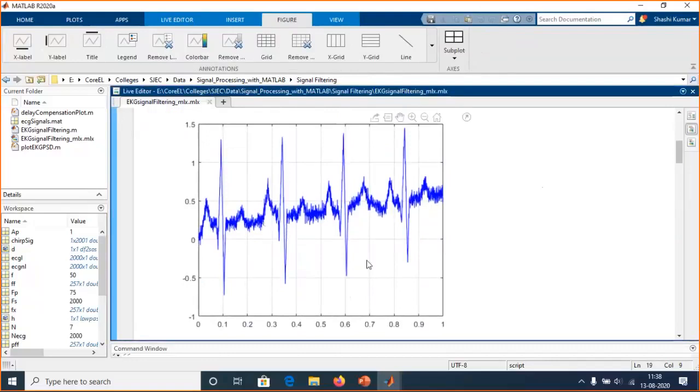All right, no problem. Basically, you see that it is not aligned to the zero axis. Even though it is slanted, we can find the difference, but it is very irregular as we move ahead. First and foremost, if you want to find any amplitude, it has to be aligned to the zero axis or the zero reference. That is when we can measure how much it is in the negative and positive scale. That process is called detrending.